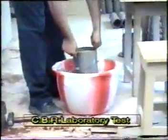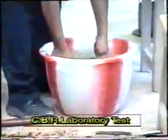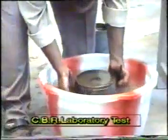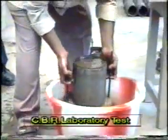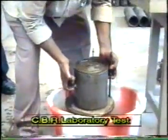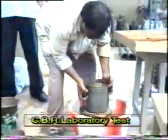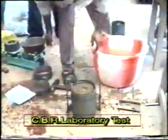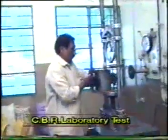Now the setup is kept in water soaking for a period of 4 days. After 4 days soaking, the mold is now taken out and allowed to drain off for 15 minutes. The sample along with the mold is again weighed to calculate the water absorption. The surcharge weight is now placed on the sample.